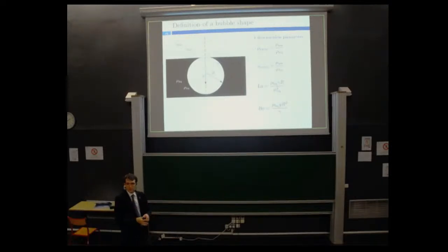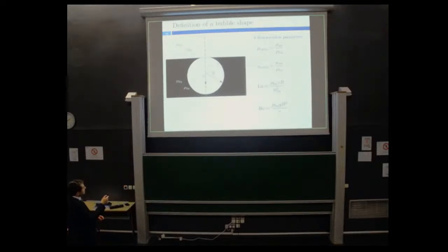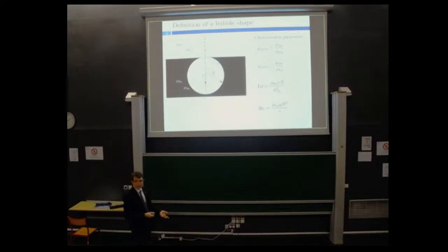This line corresponds to the small liquid film that is between the bubble and the air. And we will assume that this liquid film will not impact the bursting bubble process, so we will simulate only the black and white shape. This problem is fully characterized by 4 dimensionless parameters, so you've got them all here.